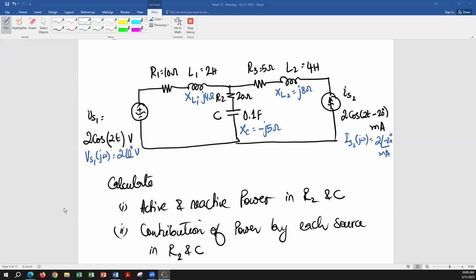Okay, we can perform nodal analysis, or we can perform mesh analysis, because in this case, we already know the current in the mesh on the right hand side. So whether we apply nodal analysis or mesh analysis, we have only one equation. Doesn't really matter. So we can apply nodal if you want. Let's call this node A.